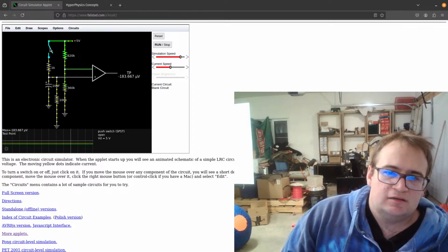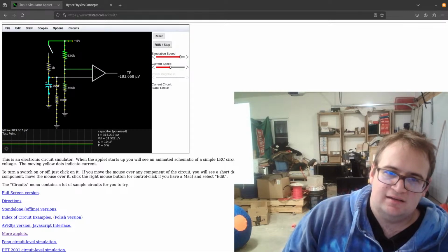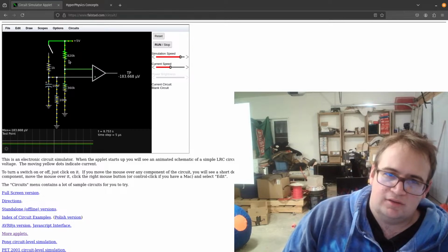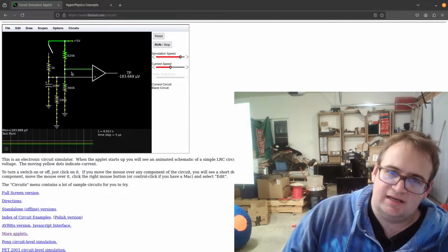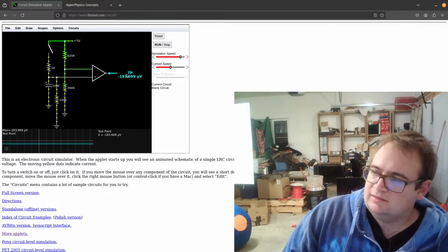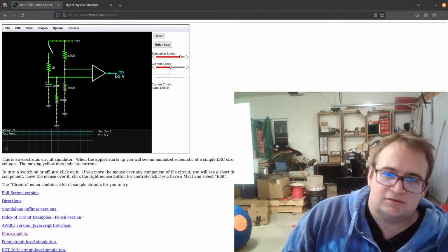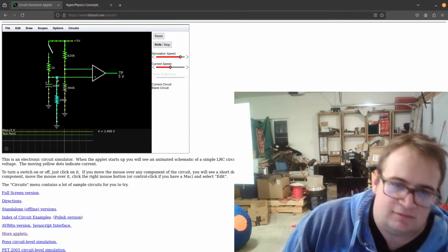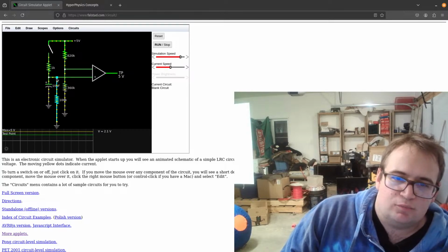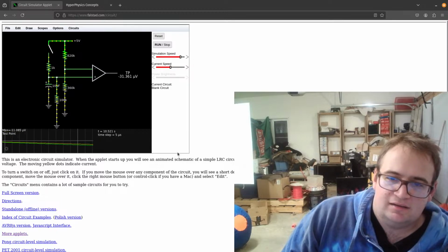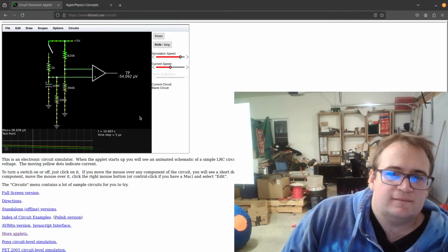Once it does that, this will discharge slowly through the 100K and eventually get to the point where the output is close to 0. Let's see if that's what happens. Click this. So yeah, we're outputting 5 volts. And then we're watching this. See, it's going down, it's going down. It's at 2.2. And there, now we're back.